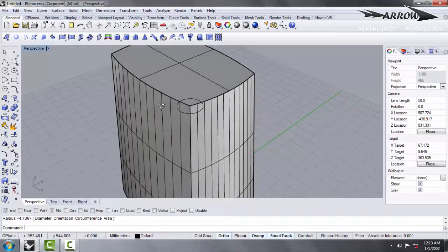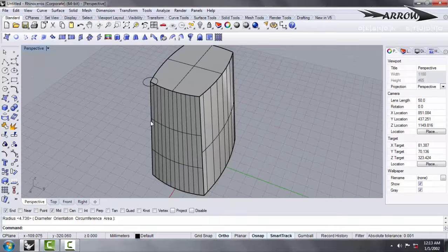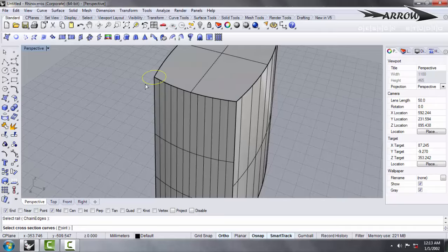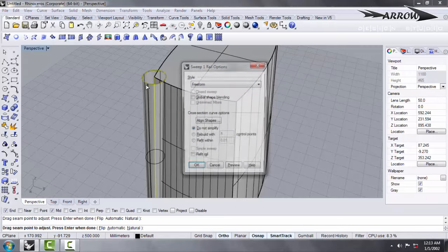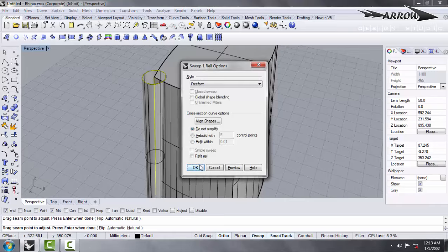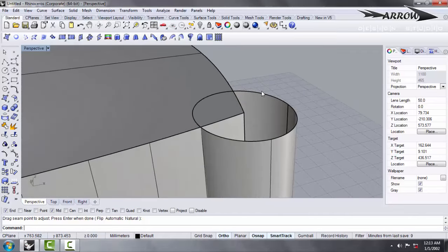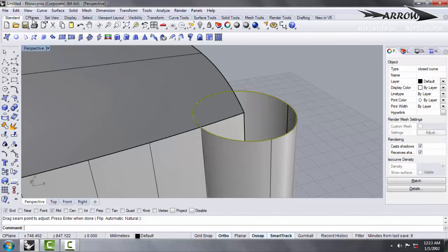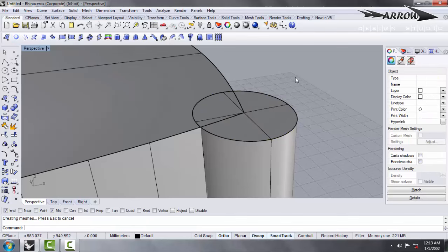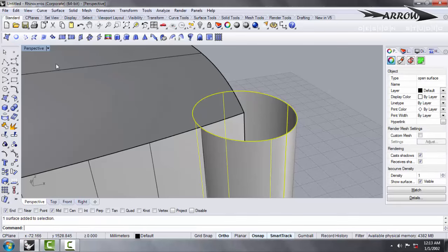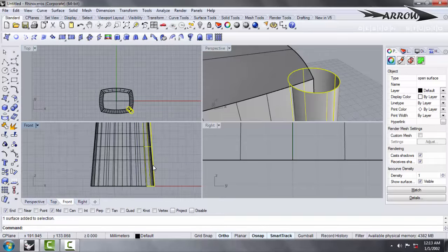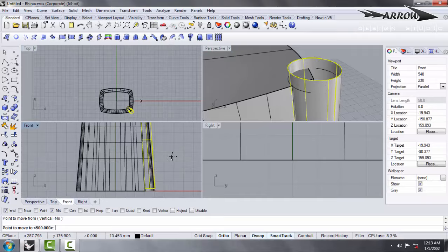Okay, I'll just make the grid snap off for a while. So this is a circle which I'll sweep, using this as a cross-sectional rail, enter, and then the cross-section curve and say enter. So you have made a circle over here, you just need to select it and again say, if possible, that's not an issue, or you can just make a tentative change in that.